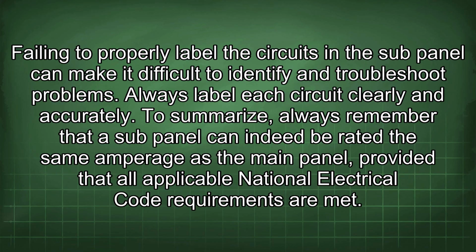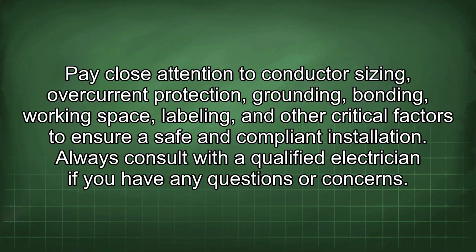To summarize, always remember that a sub-panel can indeed be rated the same amperage as the main panel, provided that all applicable National Electrical Code requirements are met. Pay close attention to conductor sizing, overcurrent protection, grounding, bonding, working space, labeling, and other critical factors to ensure a safe and compliant installation. Always consult with a qualified electrician if you have any questions or concerns.